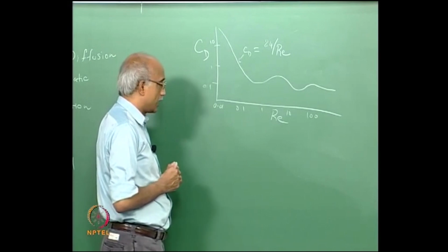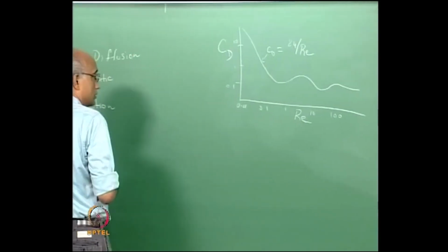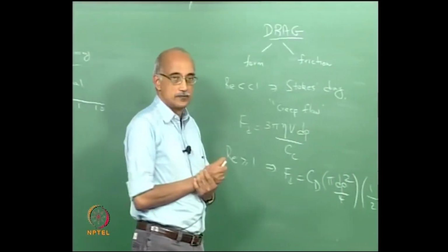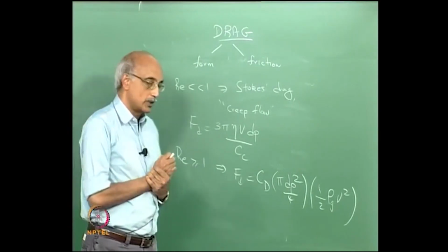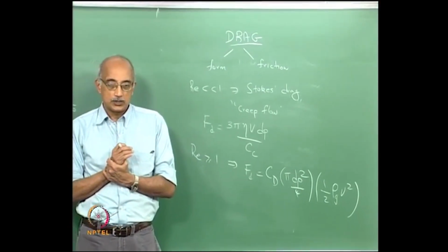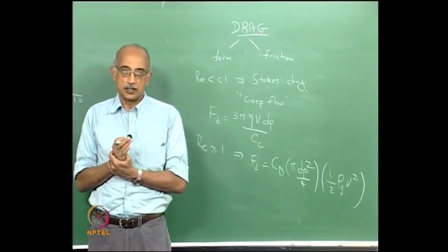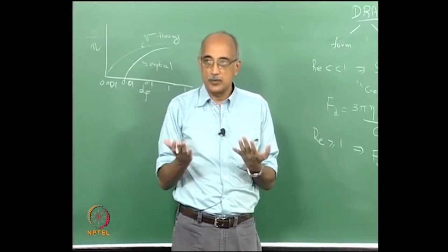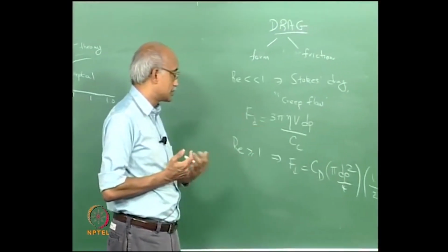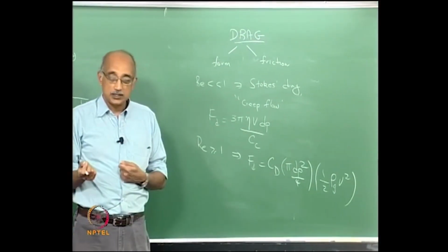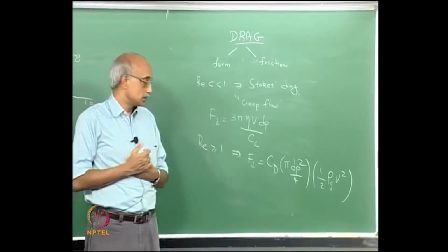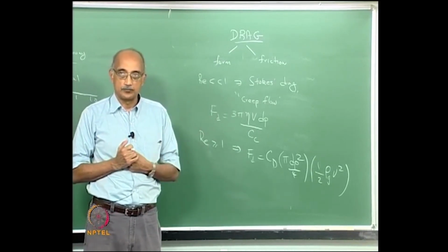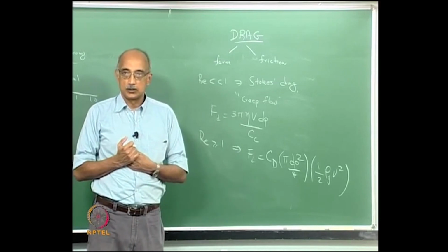So, when you look at drag force, the expression for drag that we wrote down contains a lot of useful tips. One of the questions that you always face is, do you want to minimize drag? Again, it depends on the application. If this particle is, let's say, an airplane that's flying, then you want to minimize drag. So what would this tell you? If you minimize the viscosity of the fluid, the relative velocity, and the size of the object, whether it's a particle or a plane, that minimizes your drag force.